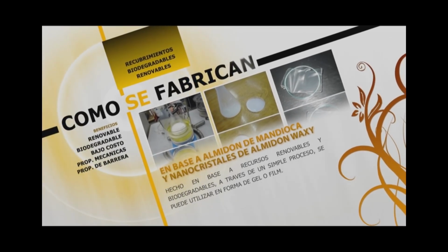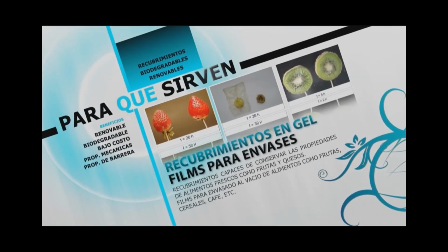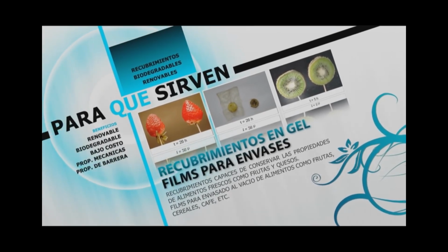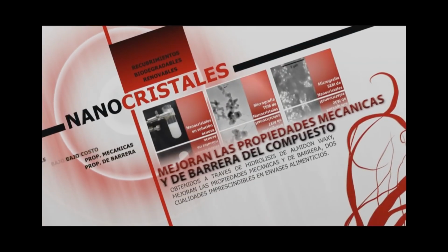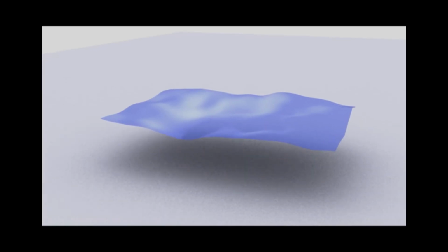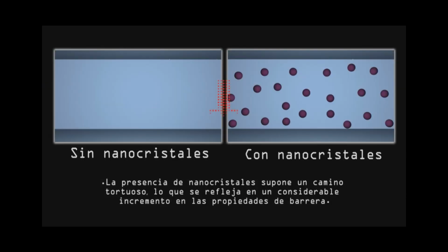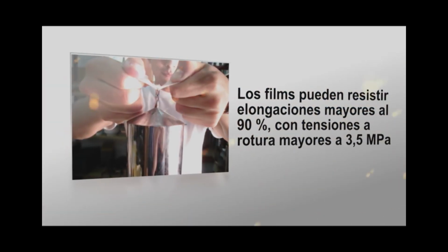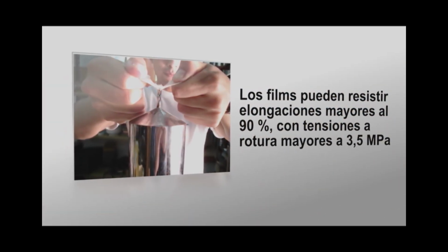And so this is how it is obtained. The starch that was used for the matrix was obtained from manioc, and the starch nanocrystals were obtained from maize. And so you can see the aspect of the food with the coating or without the coating. So this is an explanation of the barrier properties. The gas molecule can go easily in the film without nanocrystals, but when introducing these starch nanocrystals, there is a tortuous path, and it's more difficult for the gas molecule to penetrate and to go through the film.